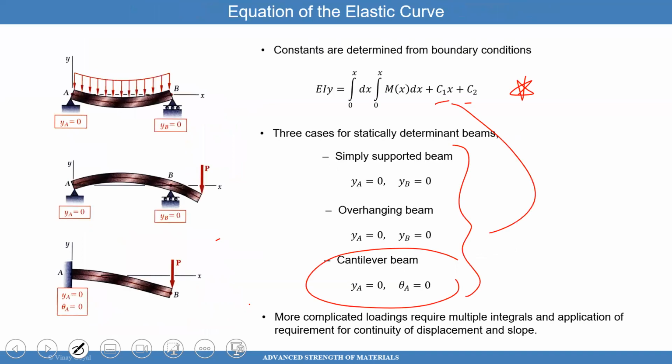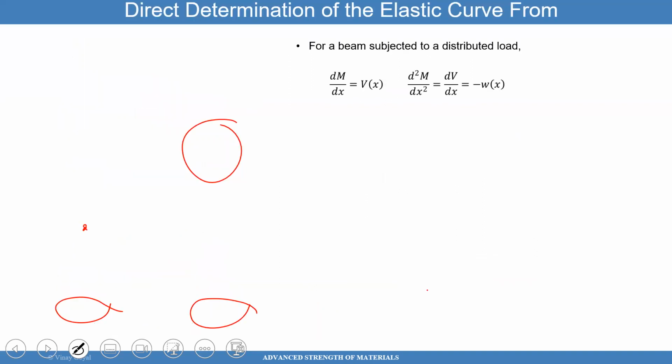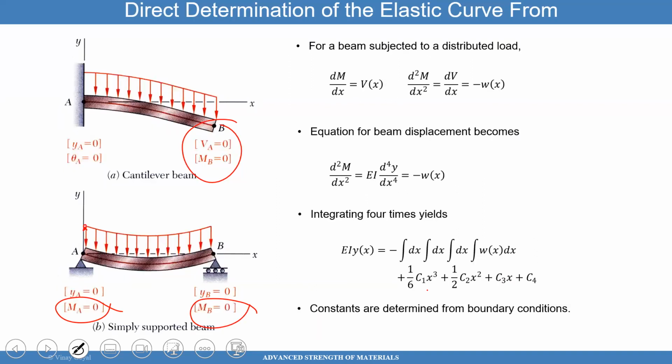If you didn't have the distributed force, you could just use the deflections and you're done. You can just use these deflections to get the constants and know how the beam deflected. But the minute you have this extra distributed load, you're forced to also examine boundary conditions beyond deflections, like moments applied and shear. And here, clearly, we don't have any bending moments or shear applied.